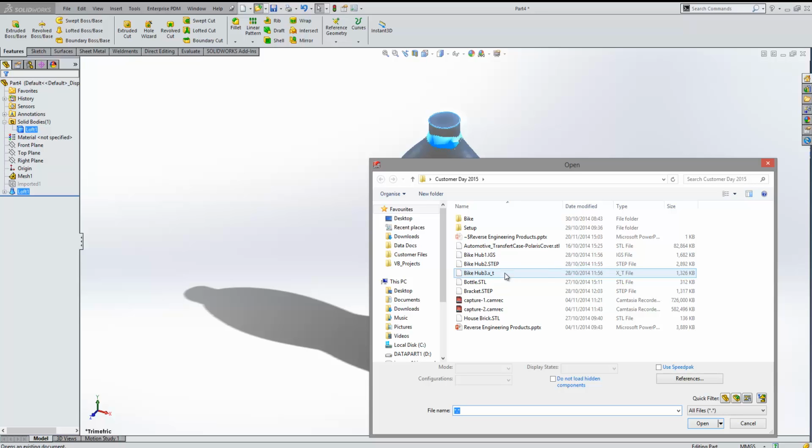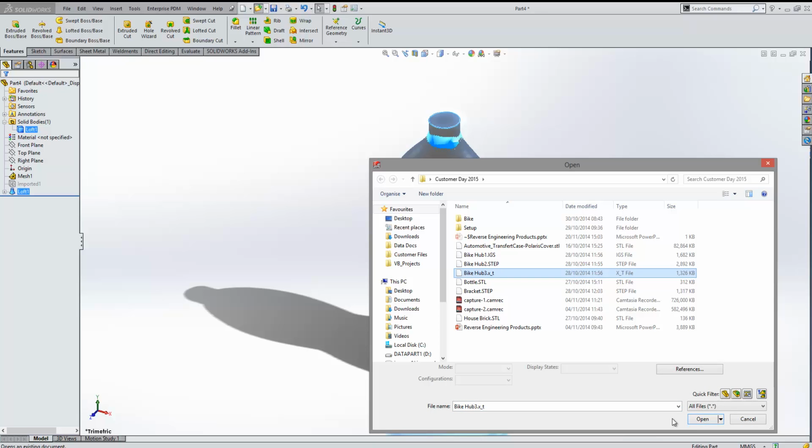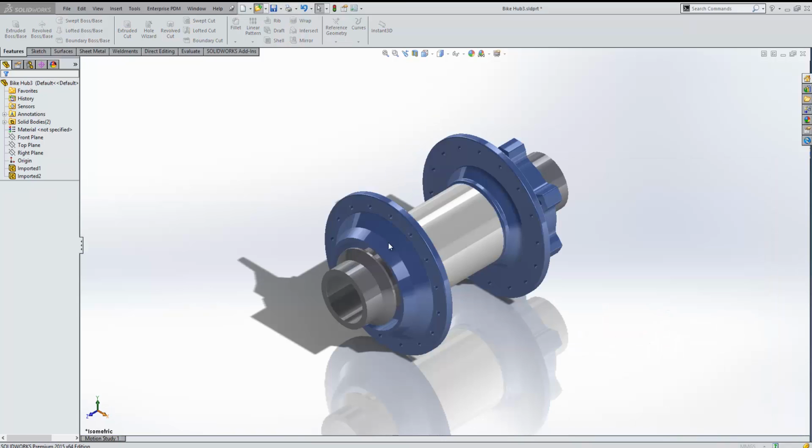You understand a Frenchman talking English badly better than you understand a Frenchman talking French well. That's because he's speaking your base language, and Parasolid is SolidWorks' base language. So if you need a transfer format, Parasolid is probably the way to go. So I'm going to open that file, and we can run import diagnostics.